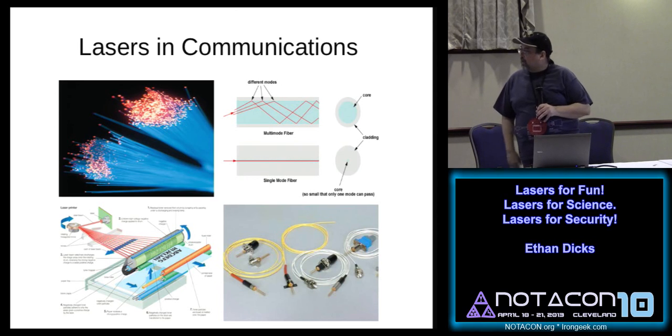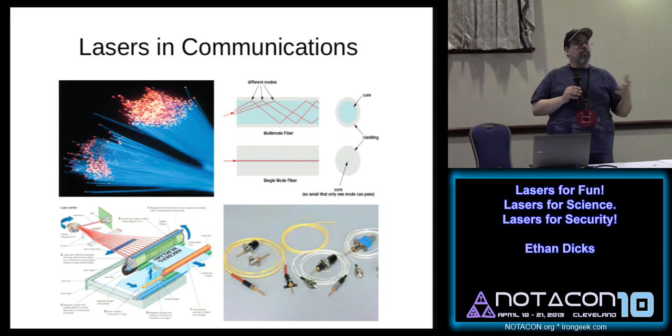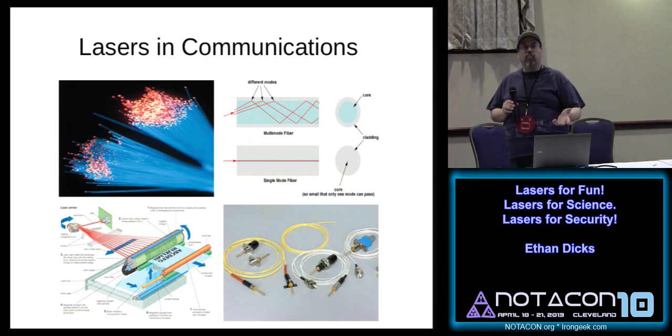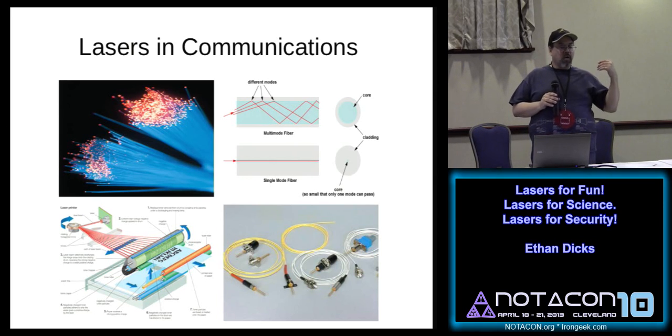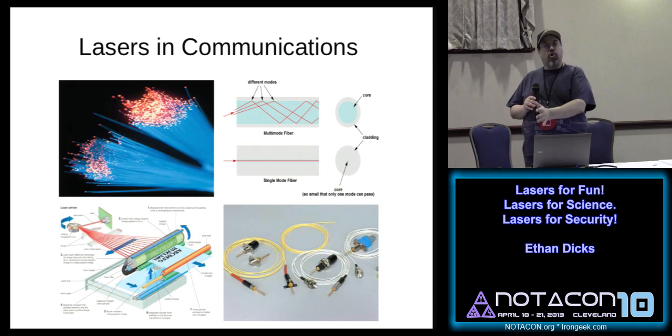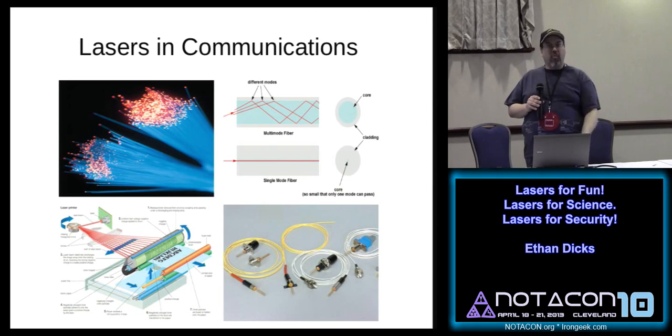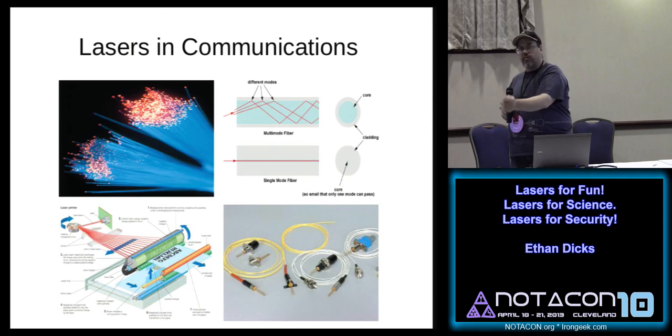And I'm lumping in laser printers under communication, because we use them to do printed communication. It's an outgrowth of xerography. Xerography was a late 50s, early 60s invention that was commercially available in the 70s. If you Xerox something, you take the original, put it on a plate, and shine light on the original. It reflects and hits a charged drum, and where the light hits the charged drum, the charge is dissipated. Where the light does not hit the charged drum, the charge retains. You rotate that past electrostatically attracted powder, which sticks to the drum, rolls onto the paper, gets fused down, and you have a Xerox.